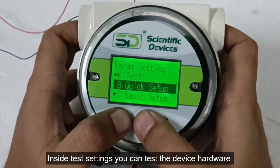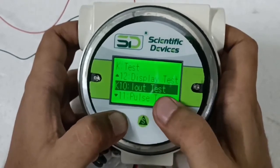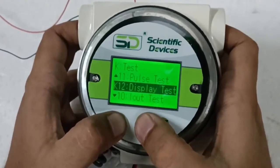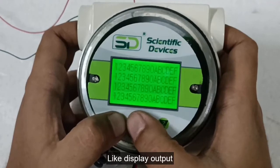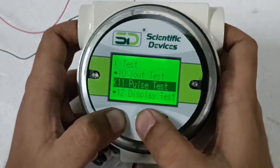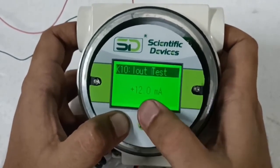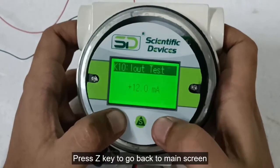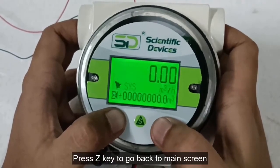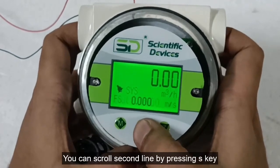Inside Test Settings you can test the device hardware, like display output, pulse output, and current output. Press Z key to go back to main screen. You can scroll second line by pressing S key.